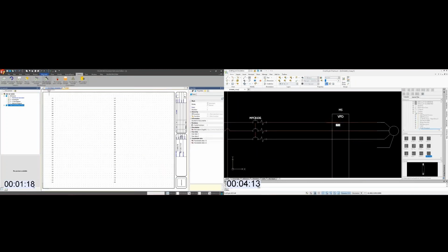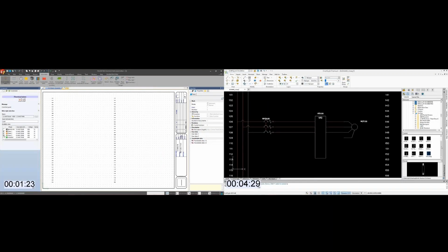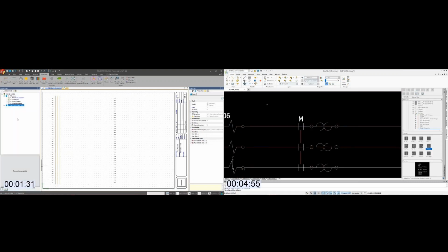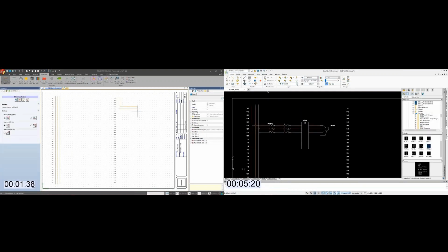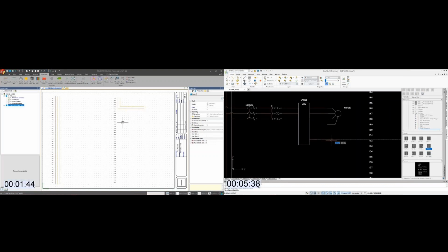Now over here on the left, on SOLIDWORKS Electrical, I'm a minute and a half in, and I'm starting to create some drawings. So here I'm going to put in intelligent wires. As you can see, I already have defined the correct wire style for each of these wires. I don't have to define that after the fact. These are fully intelligent with the physical properties of this wire, such as gauge, etc. So I'm coming over. This time I only pulled 2 phases to complete the circuit, as you would see. And so again, I've already started creating a fully intelligent drawing, populated the title block, added some intelligent wires, and starting to build that circuit. Again, all using intelligent tools such as insert wire.